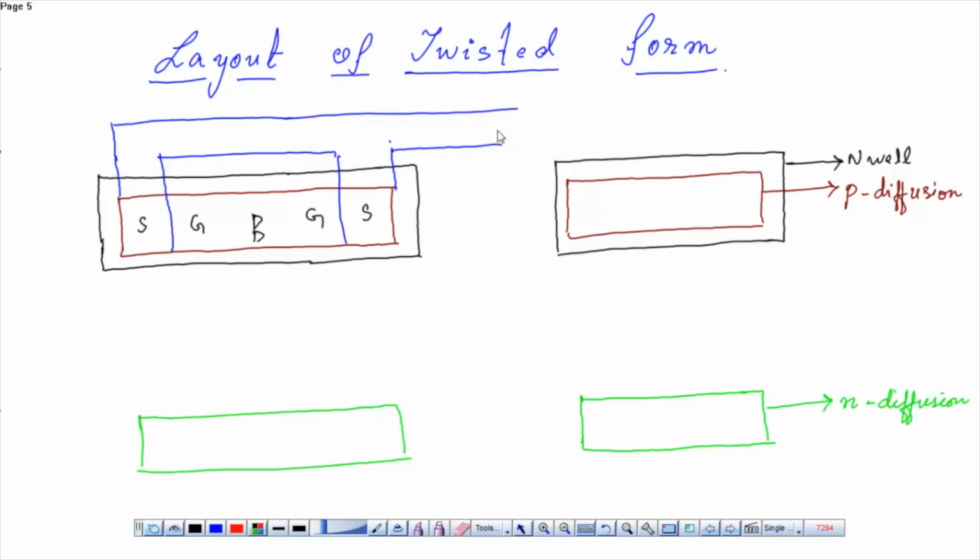Okay. Now after this, on connection with the VDD, this is VDD, above the P diffusion layer we have placed the metal layer. So how will they come in contact? We have to place a metal contact. So placed a metal contact, here also metal contact.